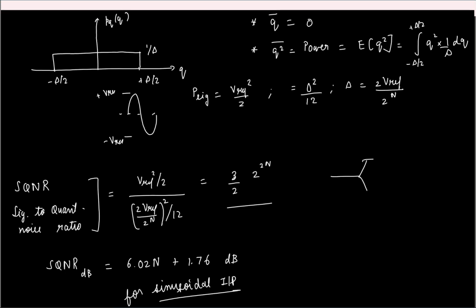So what this means is, if you have an ADC, say a 10-bit ADC, for sinusoidal inputs, the maximum SQNR I can get is around 62 dB. Now, I have SQNR roughly 6n plus 1.76. If I find the number of bits from this, I get so many bits. And usually this is how we compute the effective bits, often called the effective number of bits, or ENOB.